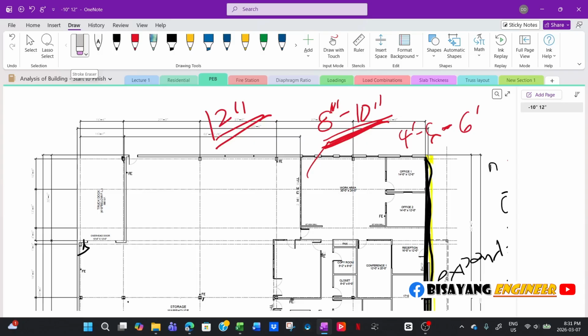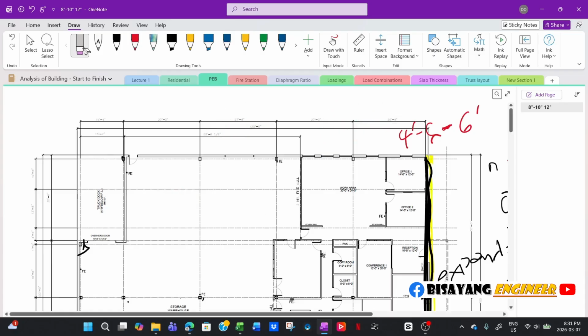So you have the bottom chord flat, but the top chord of the truss is something like that, a sloping top chord. If this is a joist, like a top chord bearing joist, then this is usually flat, and then you just slope the trusses themselves. That's why it's important to have the architectural drawing as well, and then ask what your roof layout is.